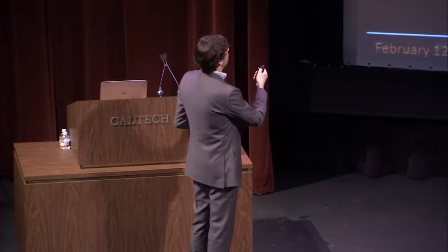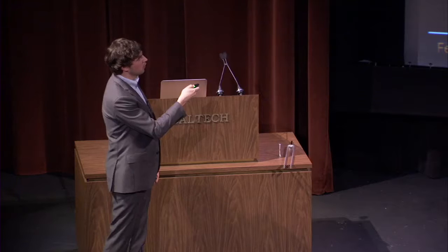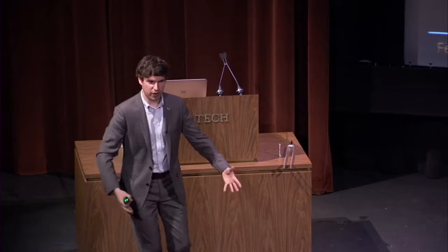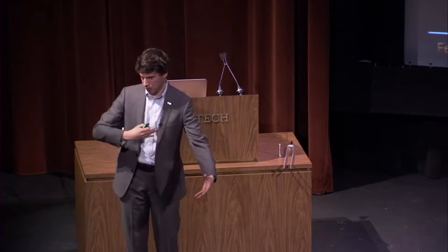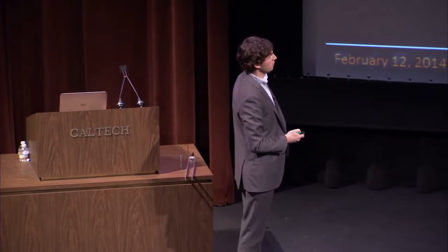So if you look, for example, at the force versus indentation curve, that's the one I showed you experimentally a couple of slides ago, what we see is at the beginning, everything is nice and smooth and elastic. When the first dislocation is nucleated, you see this drop in force. You see many of these. And all of these drops are nothing else but a defect is created, it moves. At some point, it can't move anymore. The next defect is nucleated, it moves, and so forth. So these defects are really important if you want to understand the behavior of these materials.